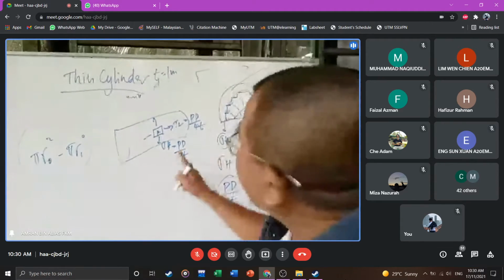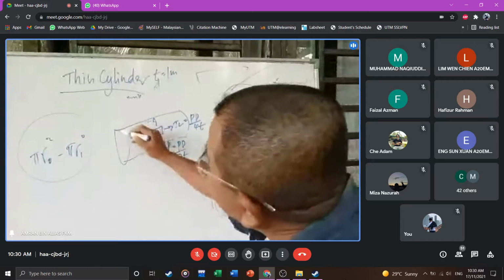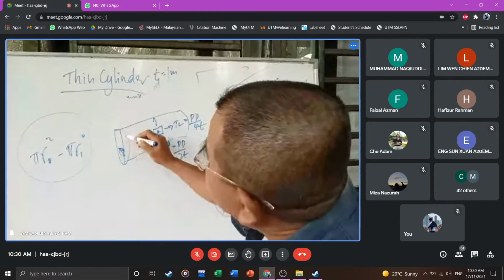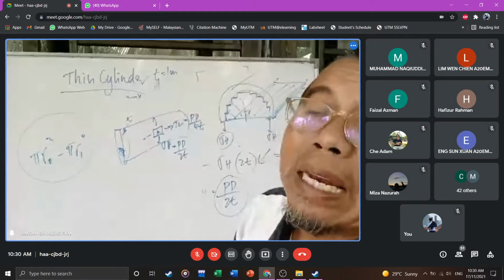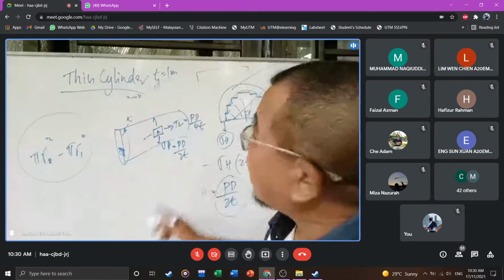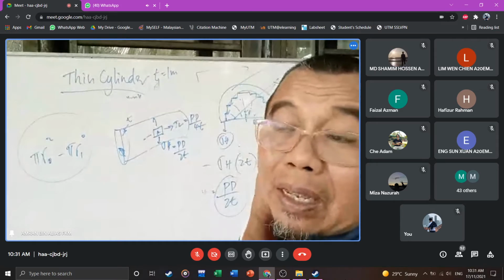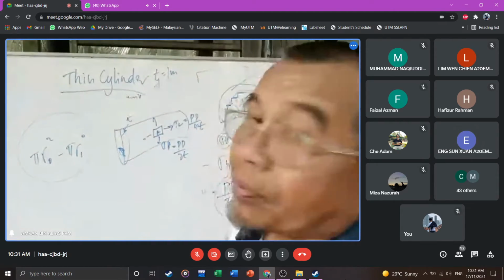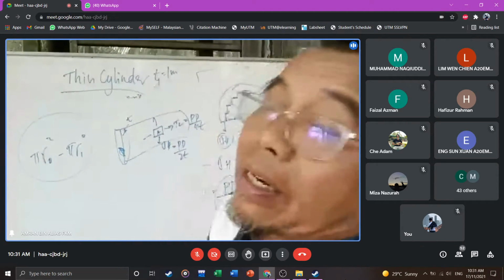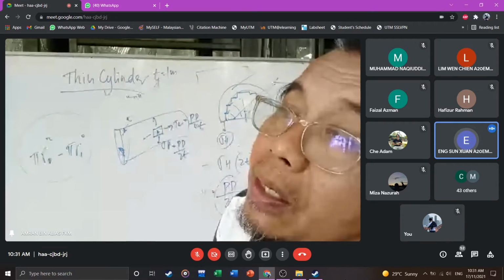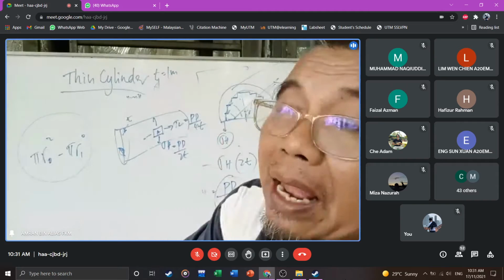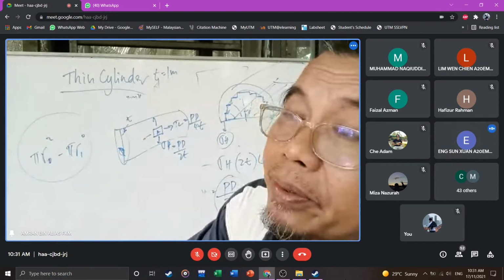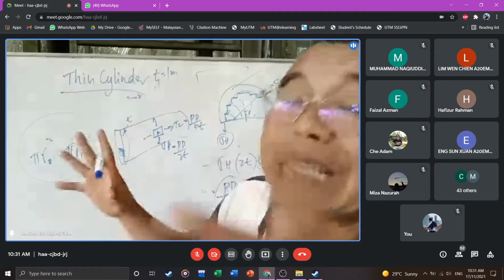You know the pressure, you know the size, the diameter and the thickness of that tin. You get the value, not? Who is higher? Sigma H or sigma L? Sigma H higher. So both are positive, right? Yes, positive. Both are tensile, right? Yes.